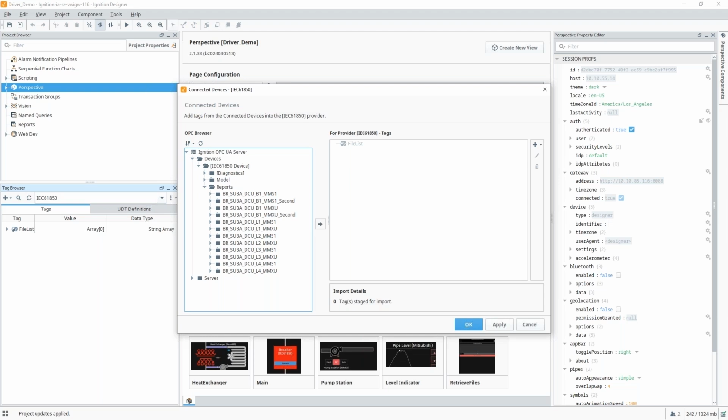One important thing to note here is if multiple systems need to connect up to the same device, reports are limited to one subscription per report. And these are all configured within the software that defines the SCD file. So if two systems need the same data from the device, separate reports will need to be developed at the SCD or IED level.